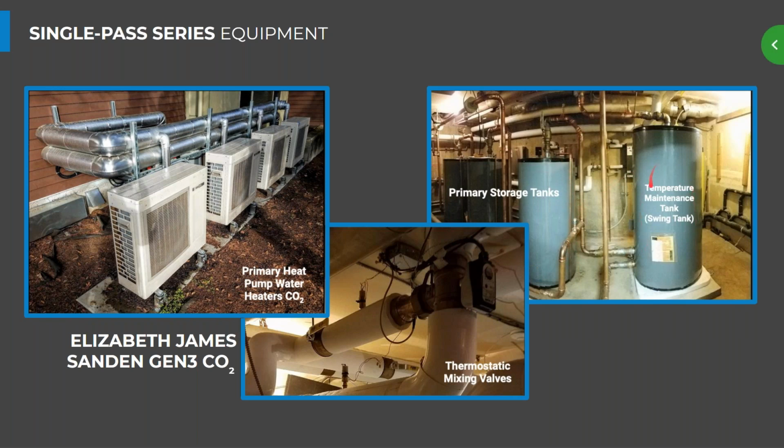We added a 4th tank and connected those to that tank, and then connected the heat pump water heaters to these primary storage tanks. And you can see that hot water coming out and going to the bottom here. And then our temperature maintenance, hot water circulation return, is coming right here and also going to the bottom of that tank there.